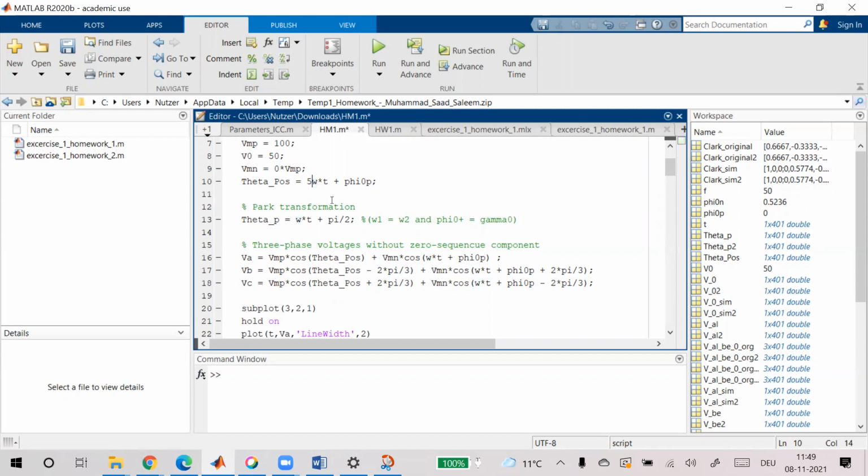Now if you add some fifth order harmonics here, let's say. So now I will add fifth order harmonics, and then just to make things simpler, I make gamma equal to 0. Okay. Now you tell me, there's no negative sequence, there's just positive sequence. Let's say third order, because fifth order actually makes negative. So let's say we have third order harmonics. There is no positive sequence, there is no negative sequence for fundamental. So what do you see? Whether you see AC or DC or both? It's a quiz for you.